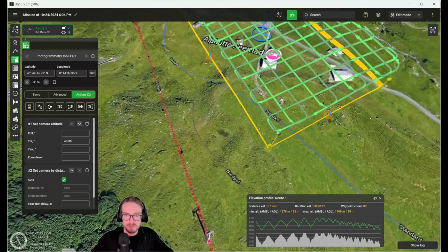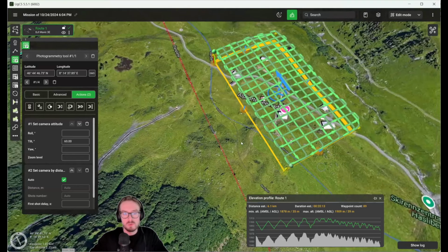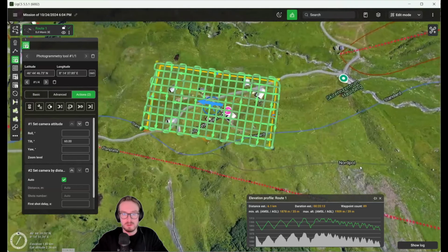Of course, in this specific case it's a wide open landscape, but in real world scenarios, very often you have some obstacles. These could be buildings, trees, towers, and so on. The problem with the Pilot 2 oblique mission, in the case of, let's say, the Mavic 3 Enterprise in this example, is that you mark out some area for the oblique mission, and then Pilot 2 will make, again, two grids overlaid on one another, but these grids will go outside of this boundary that's here.